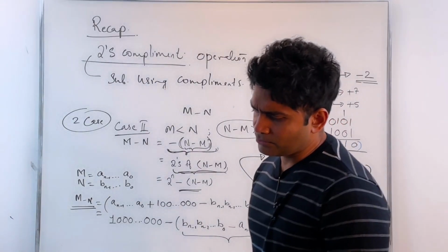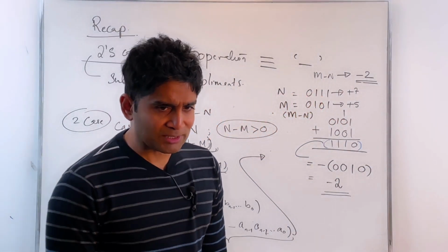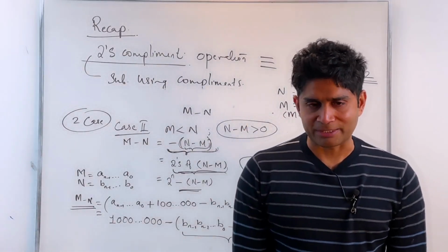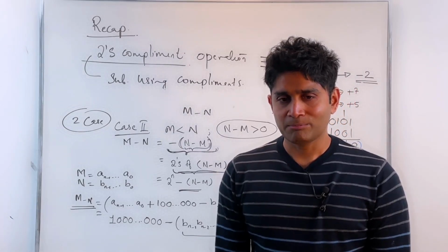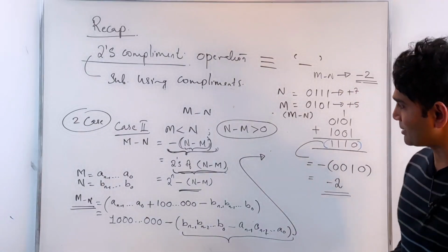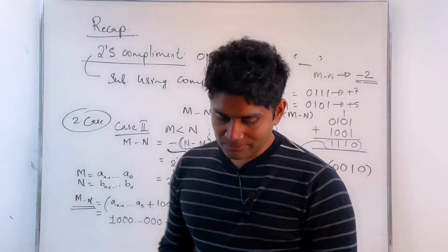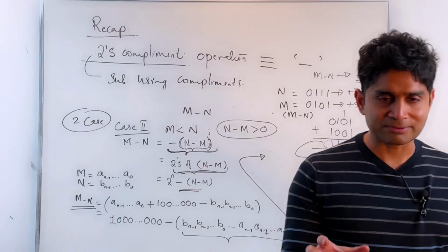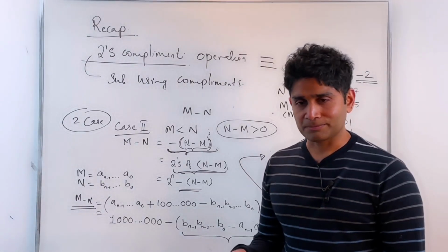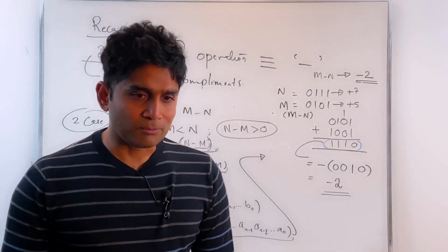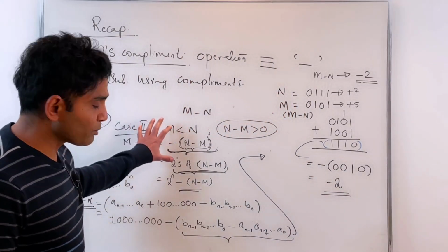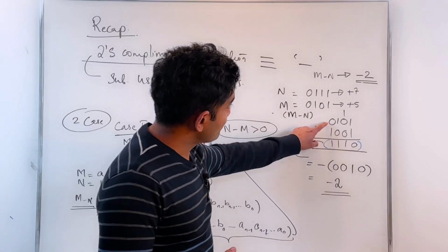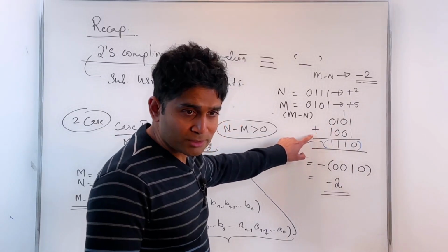No, you can design a computer logic that can do subtraction. You can design hardware that can perform subtraction. But the advantage, as you may have noticed, is that if I can design a device that can perform the addition operation, then by using the 2's complement subtraction approach, I can use the same hardware, because, as you can see here, we are doing the subtraction operation as an addition operation. You see that?